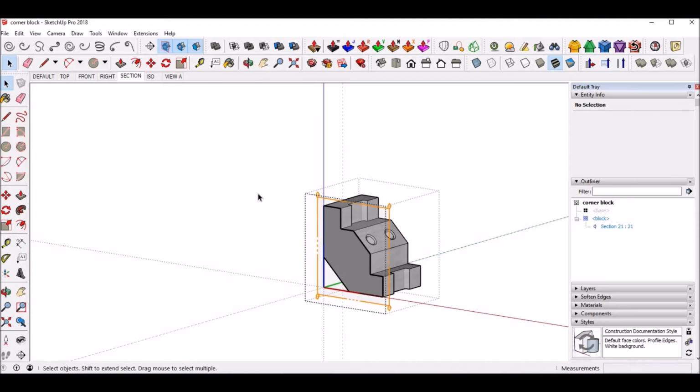and click on it. Now in SketchUp Pro 2018 and above, it automatically does this section fill with a color. We don't want a color, we want hatch marks. It won't let us do that, so I found a workaround. I discovered it one day because I was just very frustrated. In 2017 and below, this section fill does not exist. Now the section fill is actually very good when you're doing floor plans, so I'm not knocking it at all. I really like it when I'm doing floor plans, but I'm going to go ahead and turn it off.